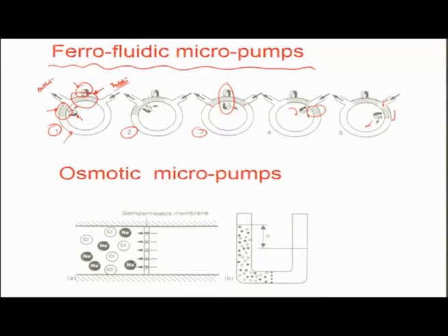And let's suppose the whole cycle is repeated, that this plug moves along with the internal magnet or the core magnet to this position. Whatever fluid was in this particular space, because of the motion of this plug, is now going away, whereas the new space that is being created is being filled with the new fluid. Again, there is a joining action, and this cycle continues many times, so that fluid can be pumped from the inlet to the outlet side.